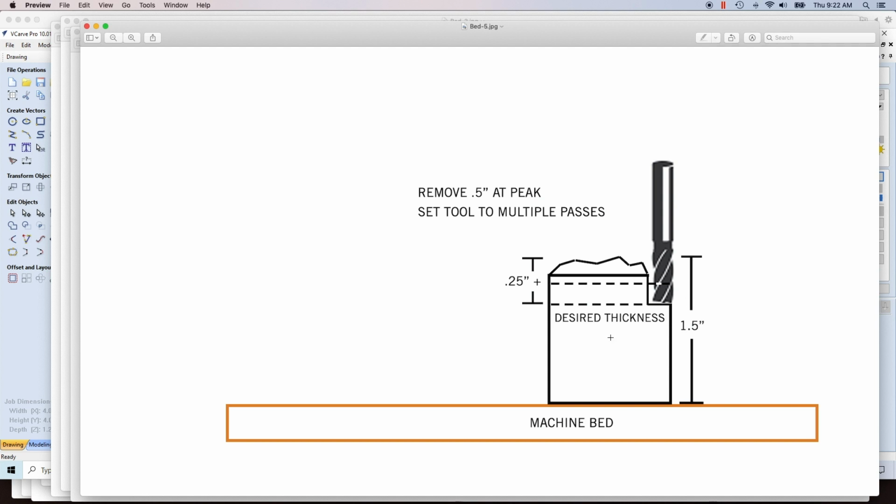So what I would do in this case is I would put the wood on the CNC. It doesn't matter, I mean, if you have one side that's a preference as the final over the other, then you'll use the opposite side right now. So you put the board on the CNC, and then we would go ahead and Z0 off the top of the material and remove some amount.